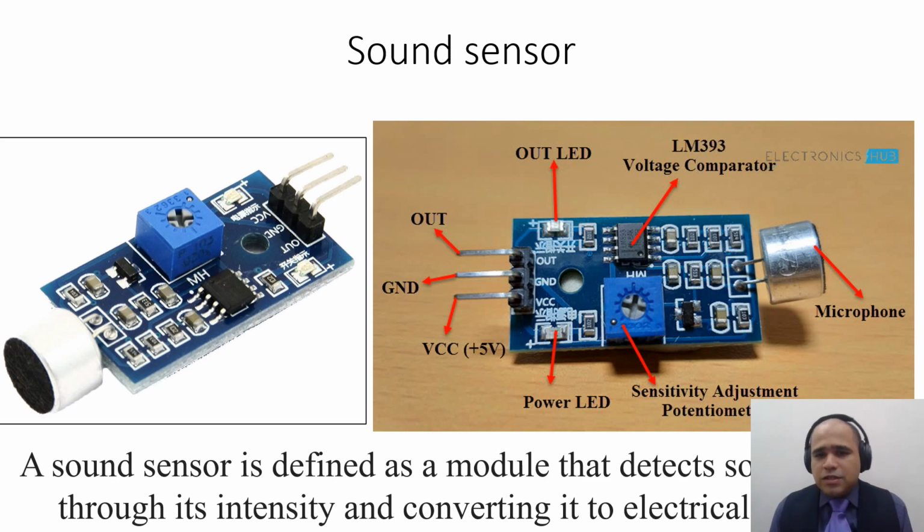So basically a sound sensor is nothing but a mic. A microphone could be an electromagnetic microphone, a resistive microphone, or a capacitive microphone, and there could be a signal conditioning circuit, as shown here, which is used to convert that audio signal into a properly readable form. That could be an amplifier or voltage comparator. If you want a clap-like operation, it will be just a binary operation.